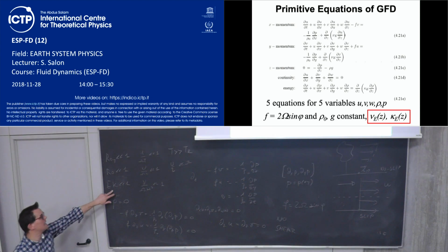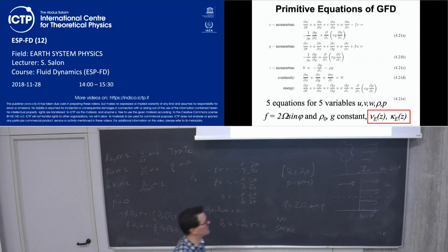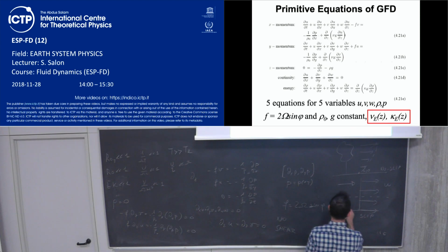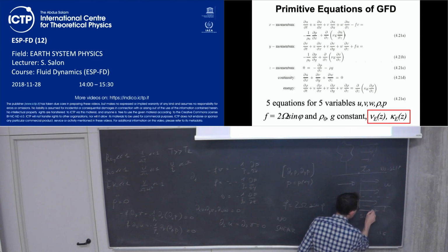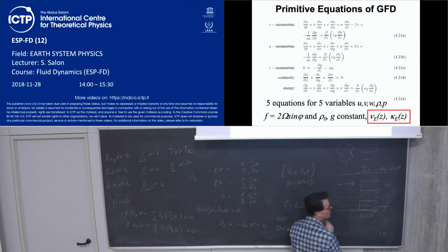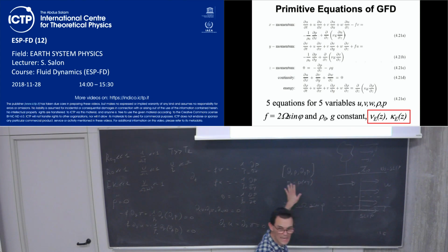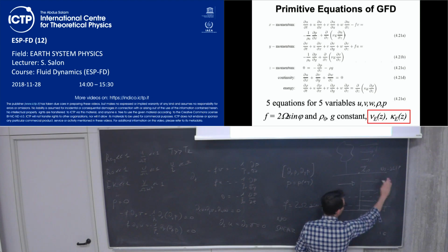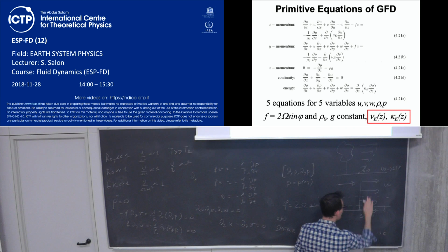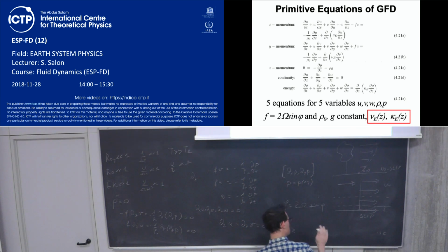Okay, so we are taking as a hypothesis that the Ekman number is much smaller than 1. So it means that we are far from the boundary. Okay, so we can consider that there will be a very small layer where we expect that this value actually will go to 0. But this is not the case now in this moment. In this moment, we are looking here, okay? We can consider the slip, and we will see a special case of slipping condition.